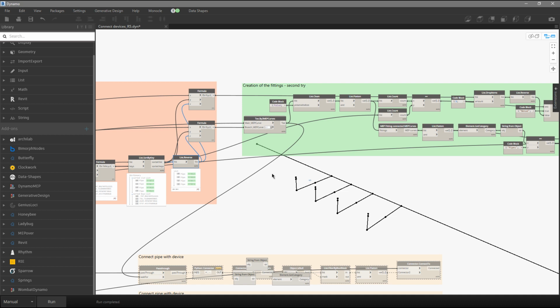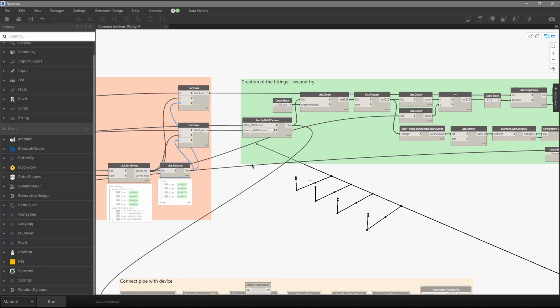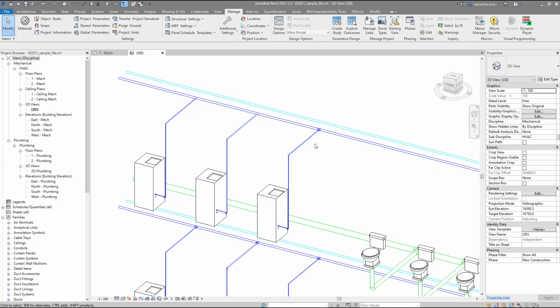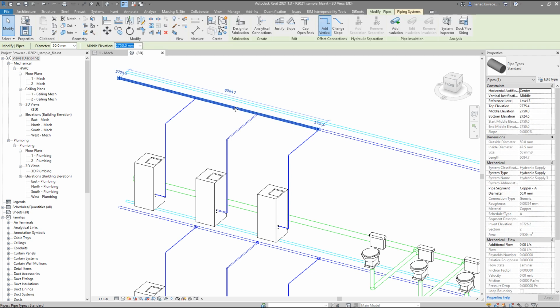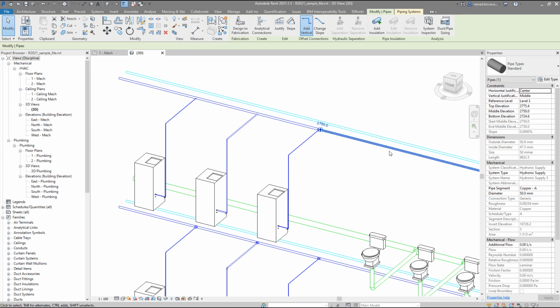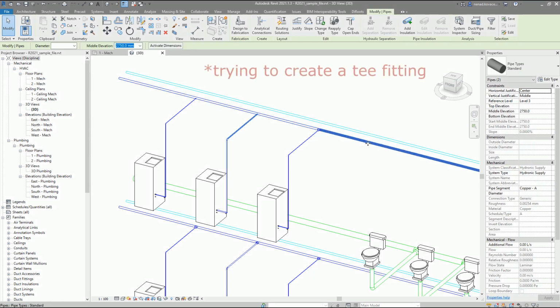Sometimes when you connect a branch pipe with the main pipe, you can have new IDs for left and right side. So in that case, we did connect at least one pipe, but we didn't connect all other pipes, which actually means again, I did assume that over here I will have that old ID I didn't have. So my ID is over here, and now I'm trying to connect this branch pipe with this pipe, and it's impossible.